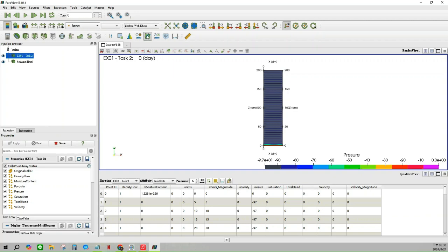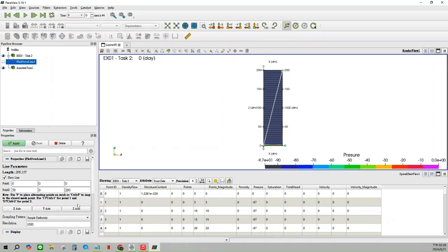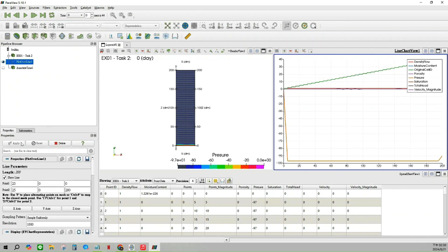Click Plot over Line, then the graph will show the line. Click Z-axis, and the line segments in the graph will become vertical to the XY plane. Click the visible icon, indicated by an eyeball, on the left side of the tree view nodes, then click Apply. A line chart will appear on the right side window of the screen.